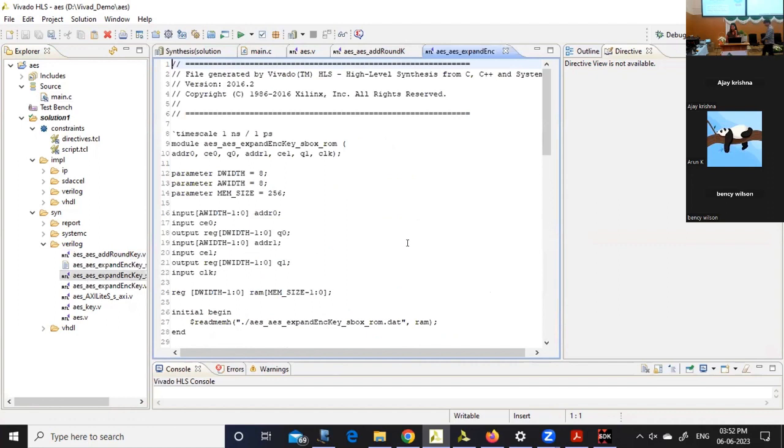In logic encryption, will the logic gates be placed randomly for each prototype or product? Also, are the keys random? Keys are not random. Key gates are random. We are placing them in random locations, and the number of key gates is random. But the bits are not random.